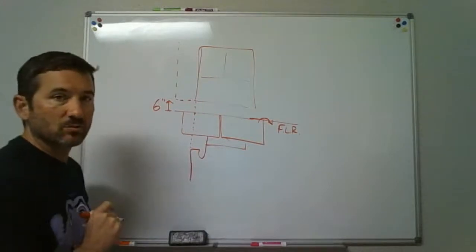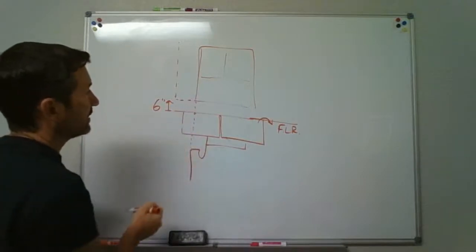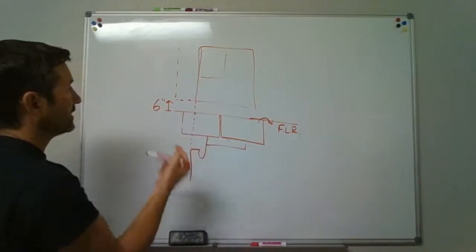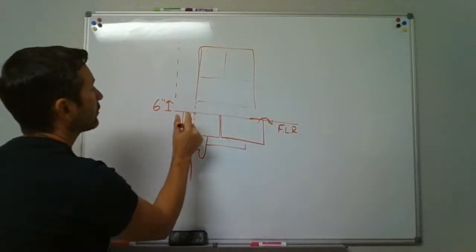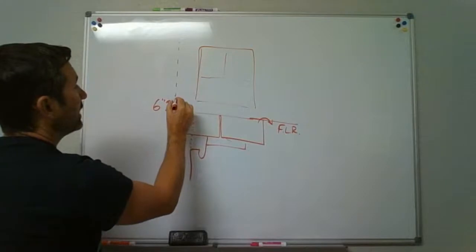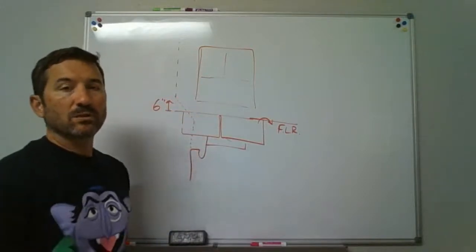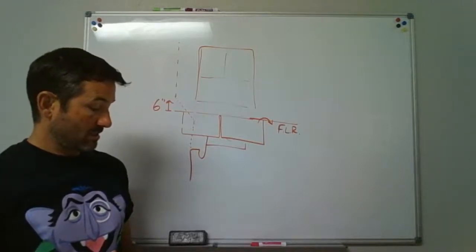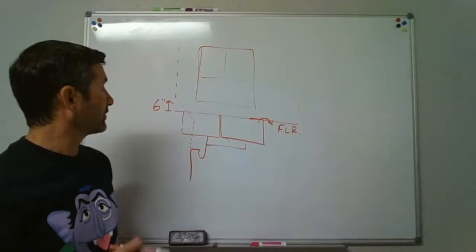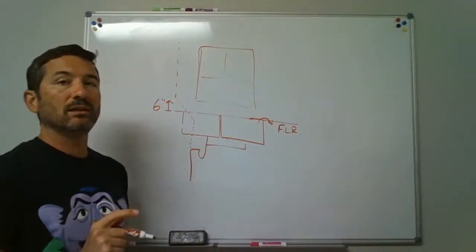But here's something else we can do. If you're like, oh no, well, maybe I can't get that. The window comes too low. I can't get 6 inches above. Remember, you can't lay it down horizontally. A 45-degree angle, if you look up the terms, horizontal pipe and between horizontal and vertical, a 45-degree angle is included in vertical.